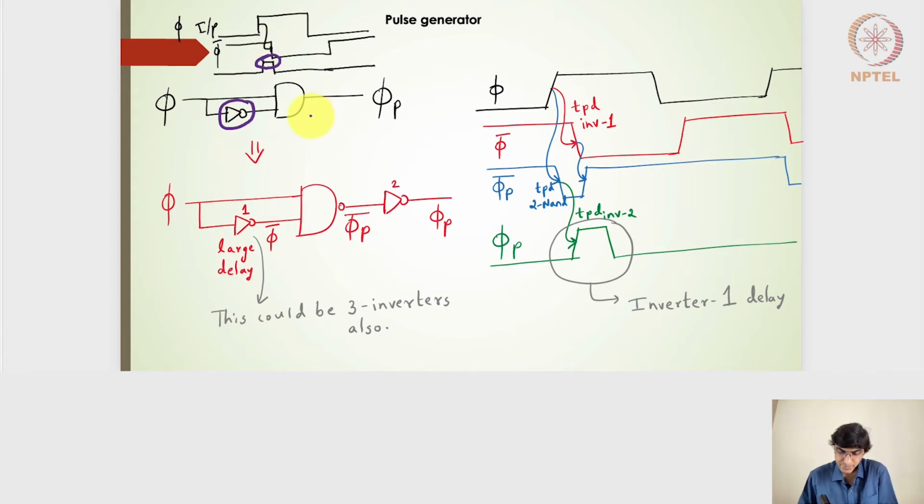In terms of CMOS technology, we cannot use an AND gate, so we use a NAND gate followed by the inverter here. So we have a clock signal given, and then the pulse signal is generated from the clock signal. Remember that in a chip design, we always have very few clock source circuits or clock generating circuits giving a clock signal, and from that we will be generating the pulse signals.